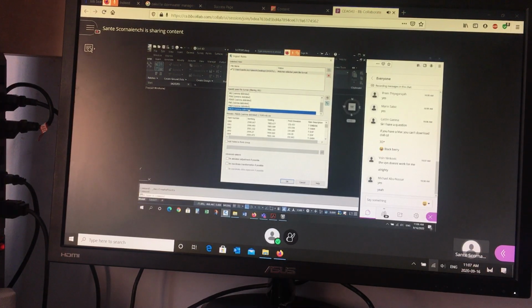The big mistake students make is to choose this one, point number, easting, northing, instead of northing, easting. It switches the x's and y's. So it's confusing. See, the easting here is 2500. If I pick this one, now the northing is 2500. So it needs to know which column represents the northing and which column represents the easting. The quick rule in this course is it's the last one at the bottom. Maybe just be careful, it may not be.